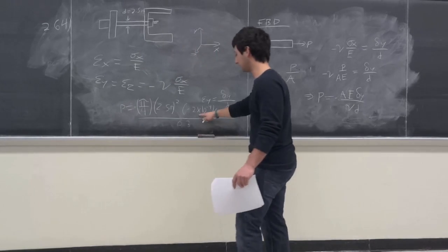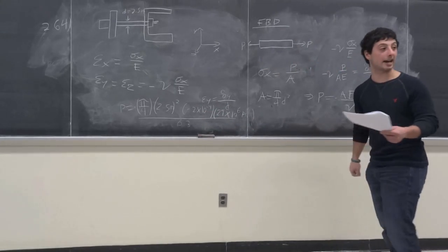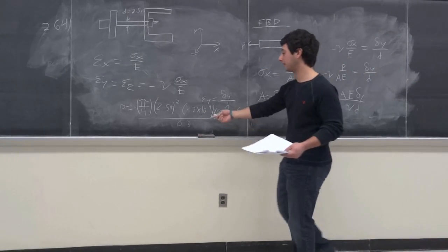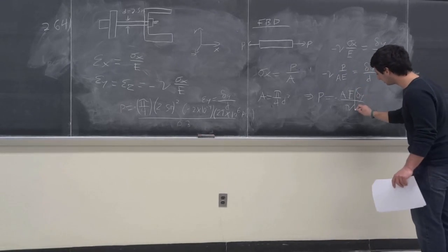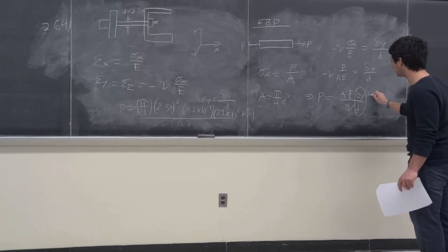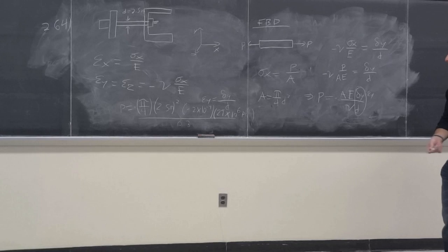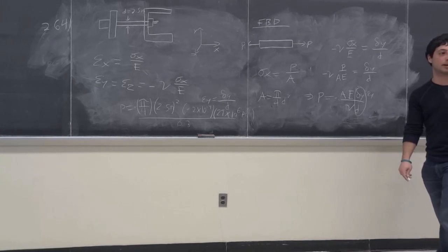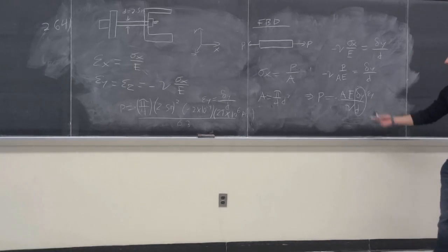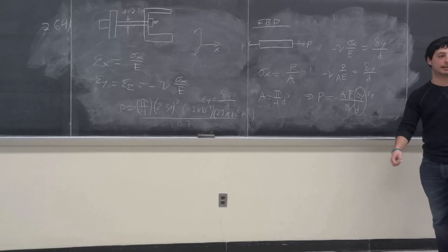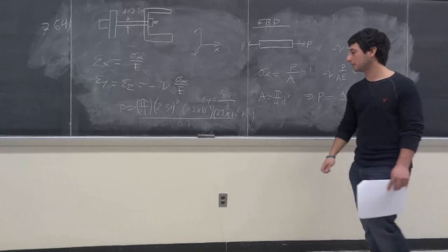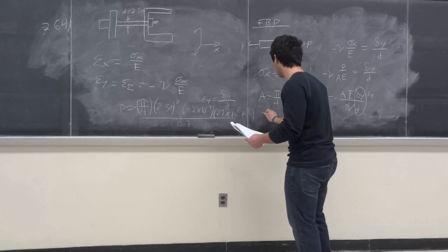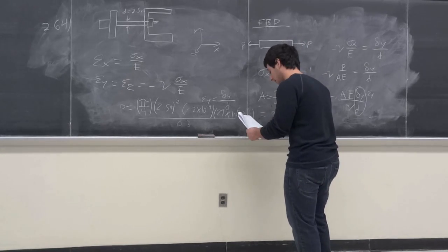And what is this value? This is a strain, this is just epsilon y. So you could just leave it as epsilon y if you want. So it's AE epsilon y over the Poisson ratio, or you could just substitute every value that I gave you. You guys follow? Okay. I should give you the value of the force. So the force is 94.4 kips.